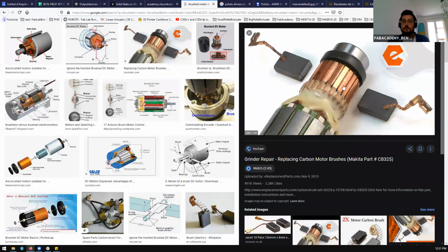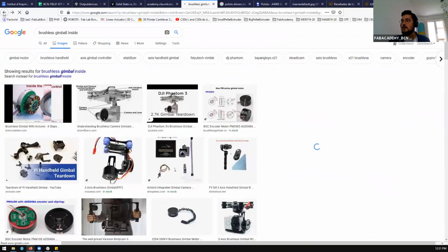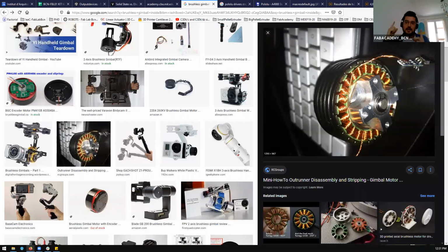From the mechanical point of view, brushless have no noise. What happens is we drive the phases really fast, ta ta ta ta ta, and that makes electromagnetic and mechanical noise on the driving electricity. So brushless usually make a really, really high pitch sound that comes not so much from the bearing, but from the driver part, like the H-bridges. But yes, brushless in general make about half the noise of a normal brushed one.